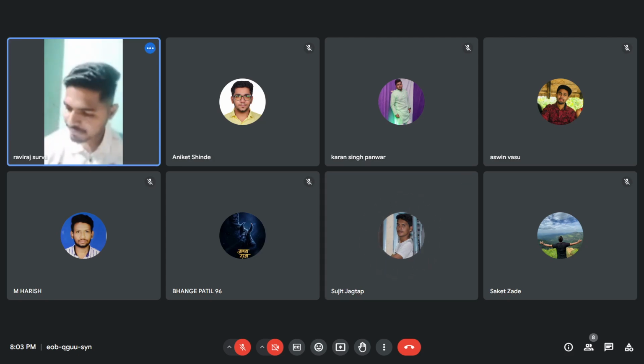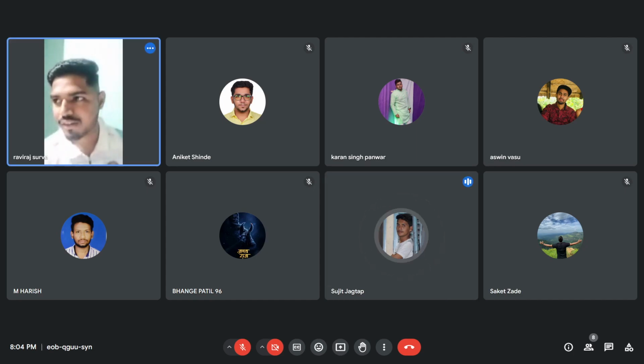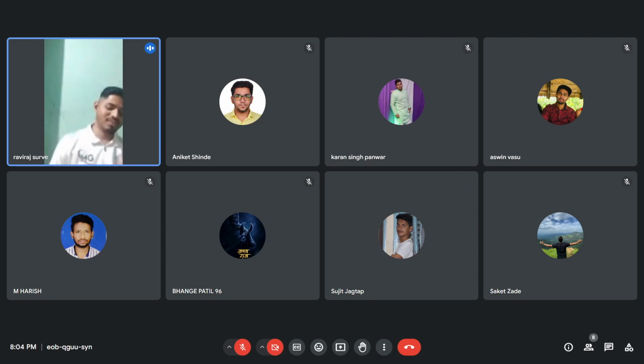Yes, bro. Okay, so Sujit, tell me the names of the safeties of compressors. Okay, bro. Some of the safeties of the compressor are: low lube oil pressure trip, second is safety valve, third is water no flow trip, fourth is water high temperature trip, fifth is fusible plug, sixth is water sensor, and seventh is bursting disc. And the next is motor overload trip. Motor overload trip. Okay.